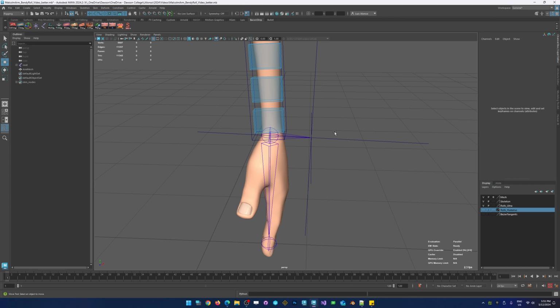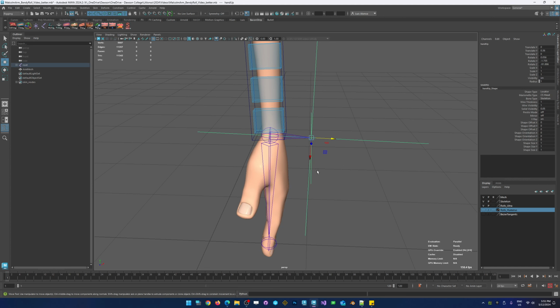Real quick thing, the reason why I have these joint nodes with these fancy visuals is because something you might not know is that you cannot include things that are not joints in a skin. So anything that's a skin gets skinned. In even inverse kinematics, you cannot have joints in an inverse kinematic chain if it's not a joint, at least not in Maya.